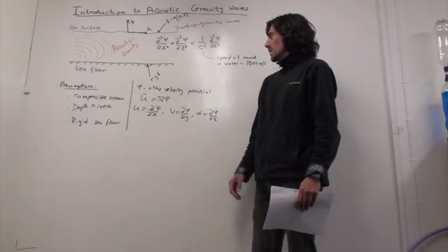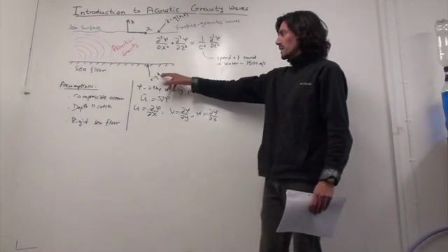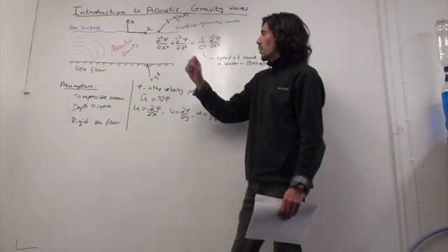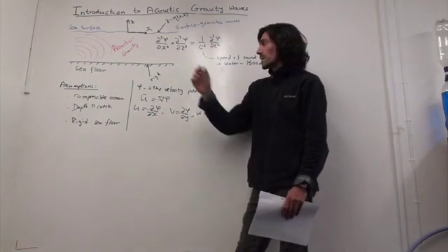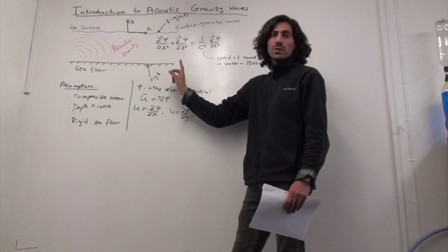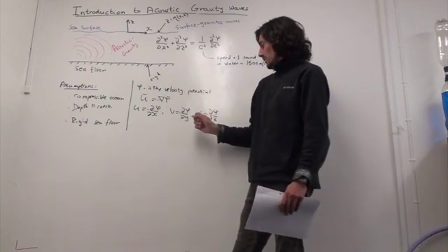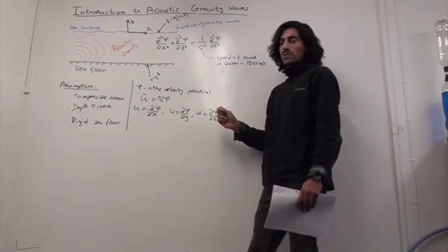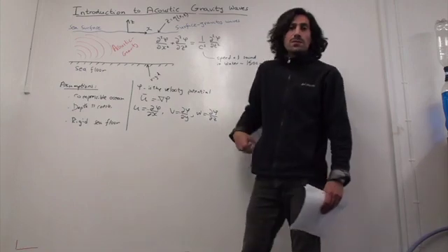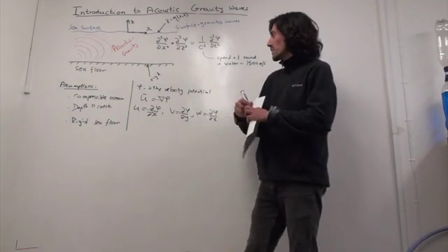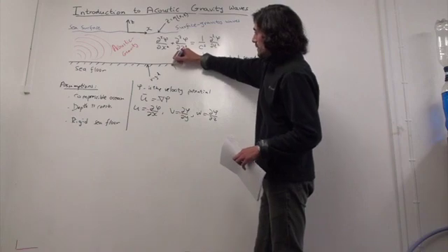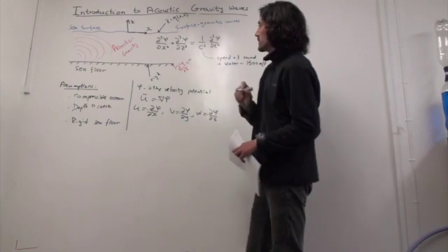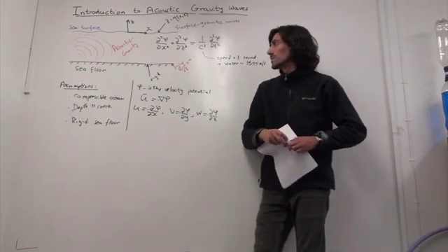Right? All right. So now, if we look at the rigid bottom, for example, the no penetration condition at the rigid bottom would say that the velocity in the z direction, w, which is basically d phi dz, if we define it positive, d phi dz would be equal to 0 there. So this would be my condition at the bottom, for the rigid case.